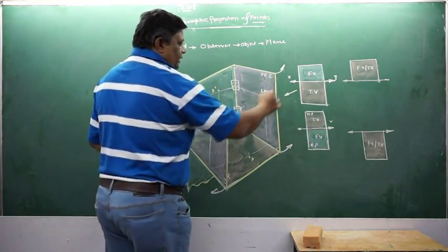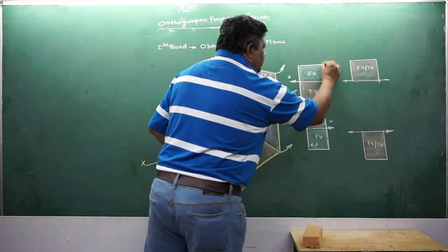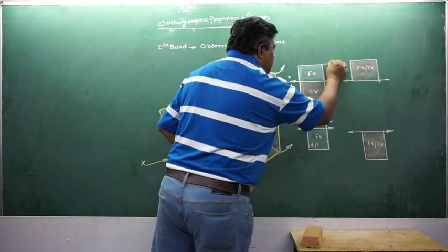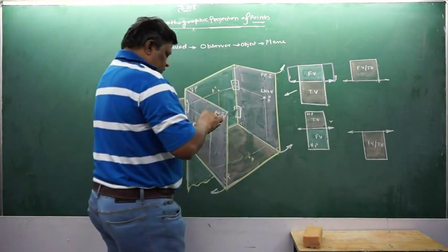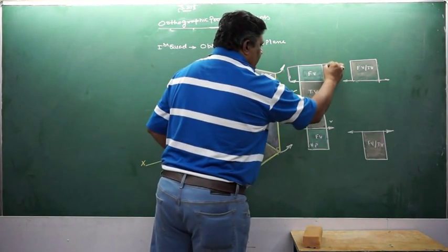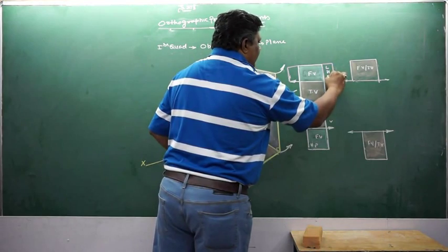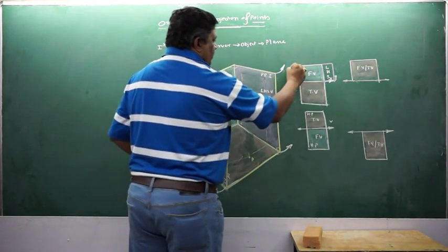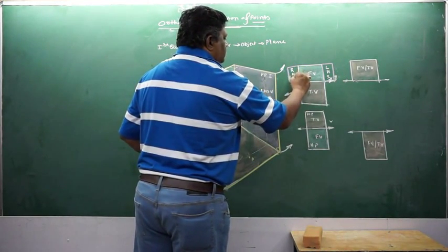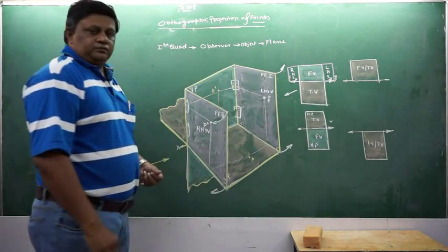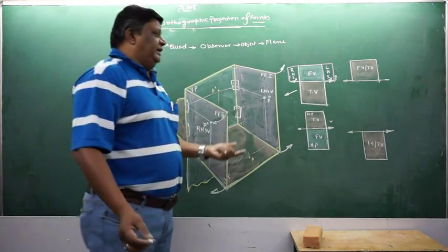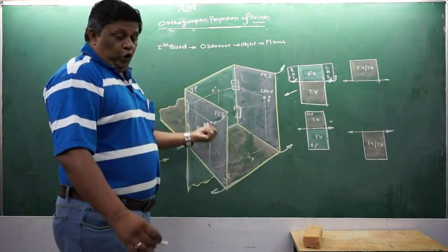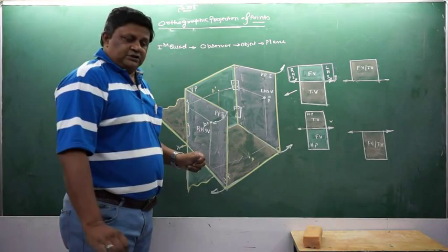So when this is open, you will see this part out here and out here. So you will be having left hand side view and this will be your right hand side view. And by what degree will I be opening it? Obviously the answer is 90 degrees because we are doing orthographic projections.